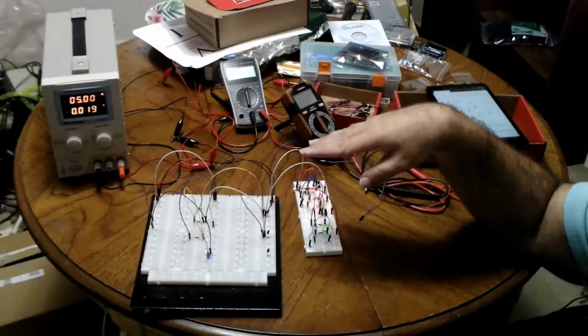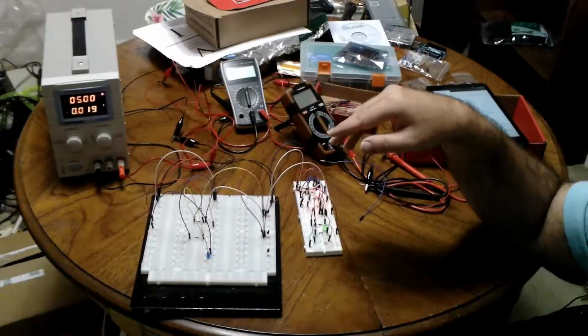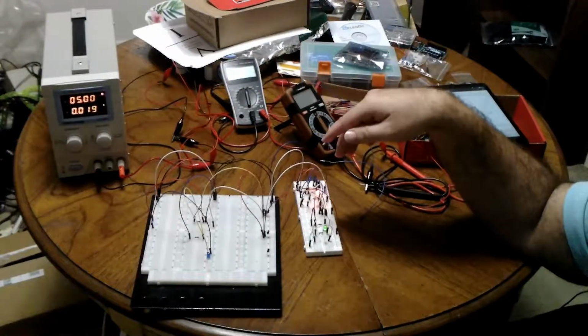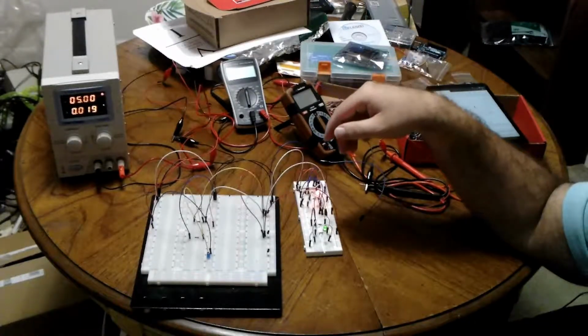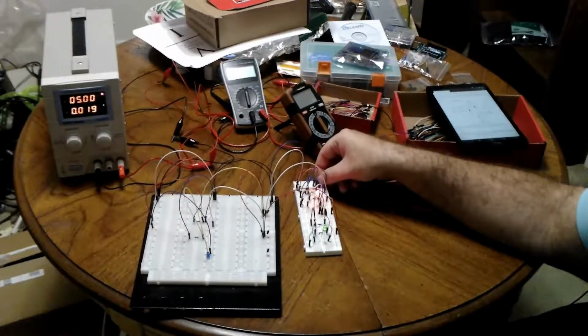One thing about BJTs is they have wastage current, but it is in the milliamps, and you can add bigger resistors and it'll work just fine, so you can reduce that. I'm using 1Ks. You could easily be using 10Ks if you want, at least on the base to emitter junction inputs. But in any case, that is our NAND gate.